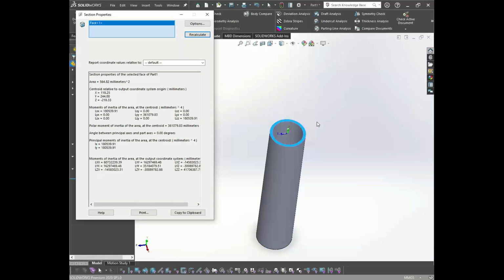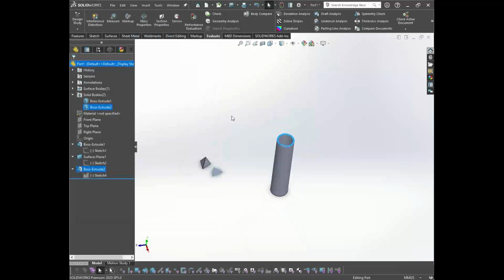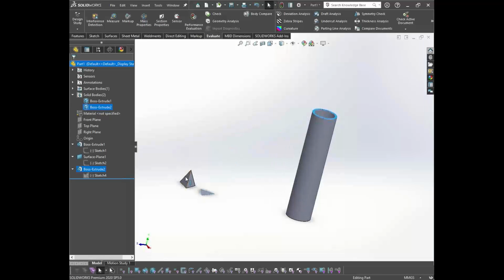When we cover the last topic in today's session, there's an involvement of all three meshes in a single assembly, and at that time you'll understand these things better, how this is graphically represented. The only thing you can understand from here is that solid elements, which capture the geometry more properly, create more degrees of freedom. For shell elements, since we are not considering a thickness, the thickness will be considered in the backend of the software.